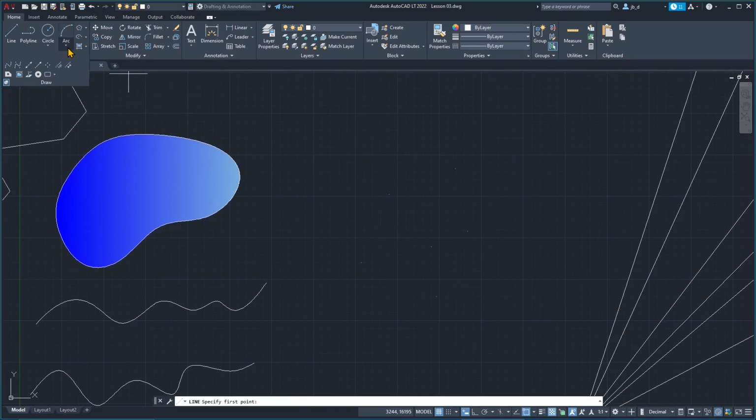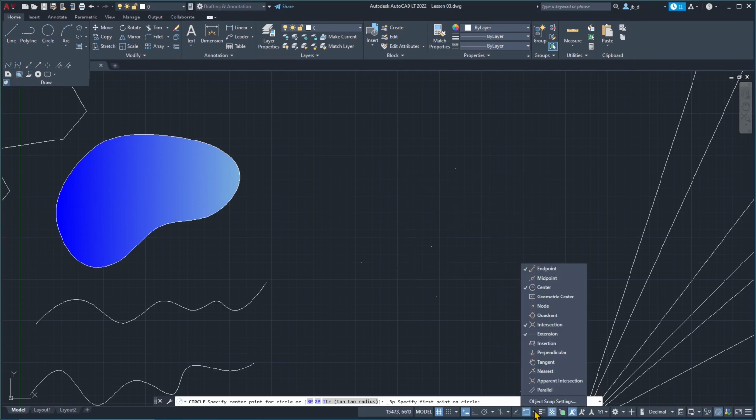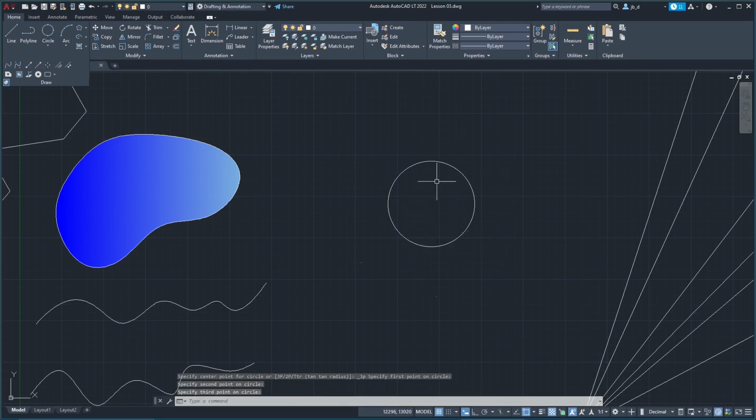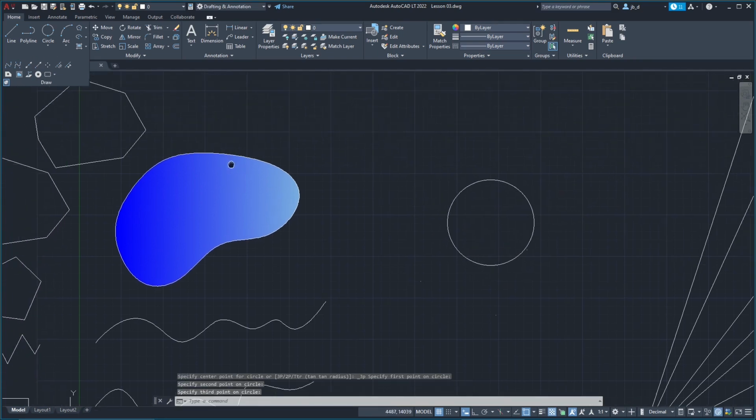You can also use, for example, here the 3 points. So you can use these 3 points to insert a circle there, but you need to activate the snap to the point. So we're gonna talk about snaps also later, but just go there. Well, in this case, they're gonna be called nodes. So you can see now I can create my circle here and place it in these 3 nodes.